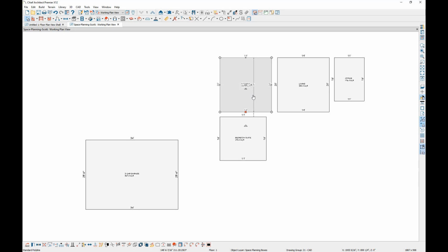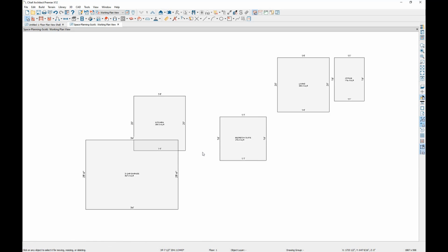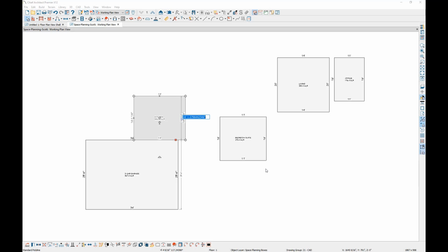And that's simply by selecting them, and you can grab this move handle, hold down your control key to get freeform movement, and then you can just start stacking them around wherever you'd like. In this type of a design, you could overlay these and you can edit the box. So if you know that it needs to suit a specific size, you can resize that, and you have these temporary dimensions so you can type in an actual value.